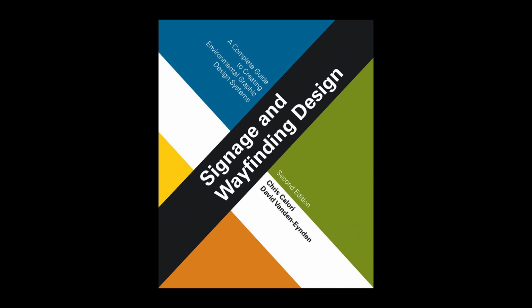Thermal stone finishes are more roughly textured, created by heating the stone surface, causing it to break along the crystalline structures inherent to certain granular stones such as granite. Cleft finishes are also rough textured, imparted along the natural layers inherent to certain sedimentary stones such as slate. See figure 6.71.